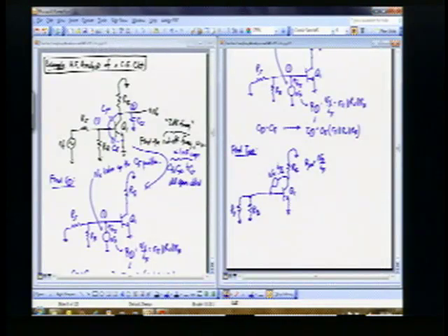I'm going to write it in terms of our nodes here. So this then is equal to all the resistance in shunt with node 1, that's R1 circle, plus all the resistance in shunt with node 2, that's R2 circle, plus GM times R1 circle times R2 circle. Okay, and that's just an equation that you're going to have to memorize if you want to do it this way. Okay? So you have to memorize the equations for the things that are not in shunt with the nodes.